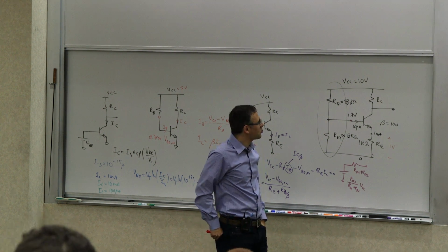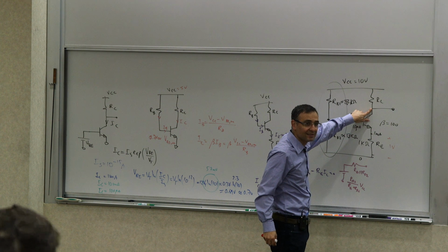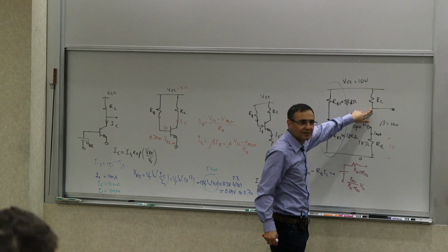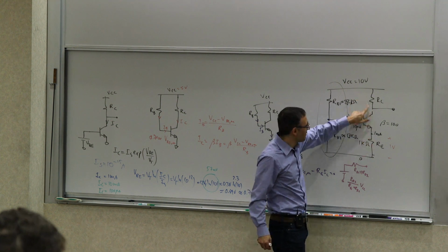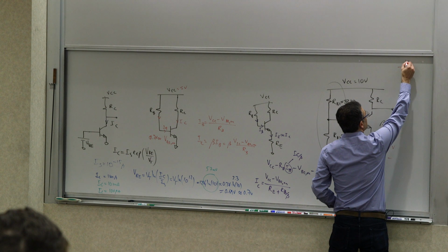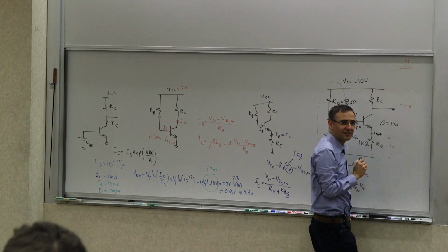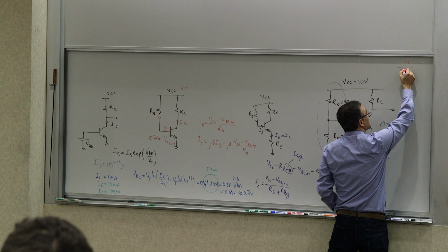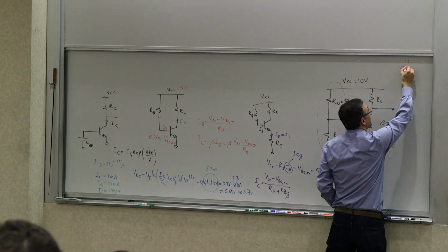How low would it go? What voltage would it be operating normally at here? 9.9 volts, right? 100 millivolts below, because it's 1 milliamp times 100 ohm. So if this is 10 volts and this is 0, it's nominally staged here. So you can imagine that it will not support very large swings, because if the swing becomes a little bit larger than that, then it gets clipped,